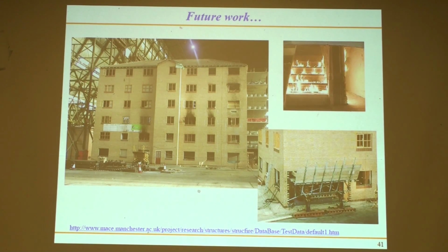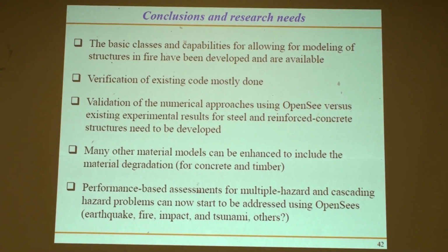And my second question is, when you do analysis, do you somehow incorporate some uncertainty in the temperature or locations? No. Okay. That's all good things to consider. Sensitivity, things that Professor Joel Conte and Michael Scott talked about, doing uncertainty and sensitivity analysis in an automated way. That's a whole lot of work that can be done in OpenSees to extend. So for each material model, if you want to do a sensitivity analysis, and you want to do DDM or FFD that they were talking about here, you need to have that implemented into your material model. So it's another extension.